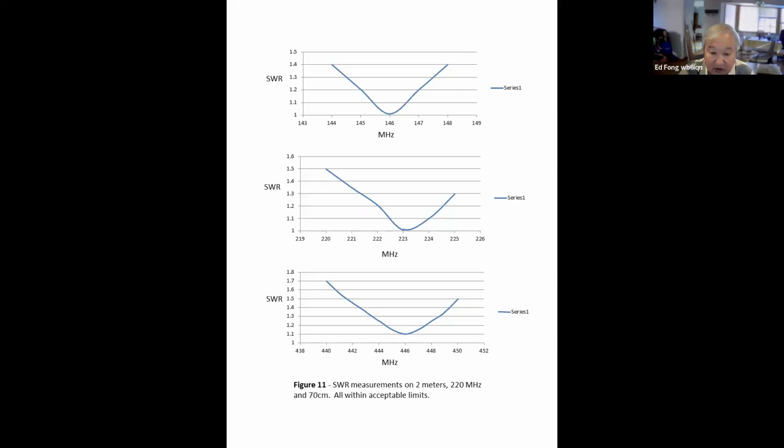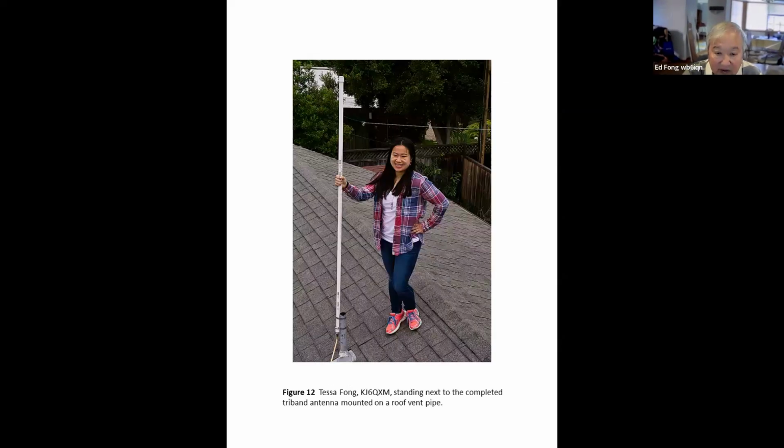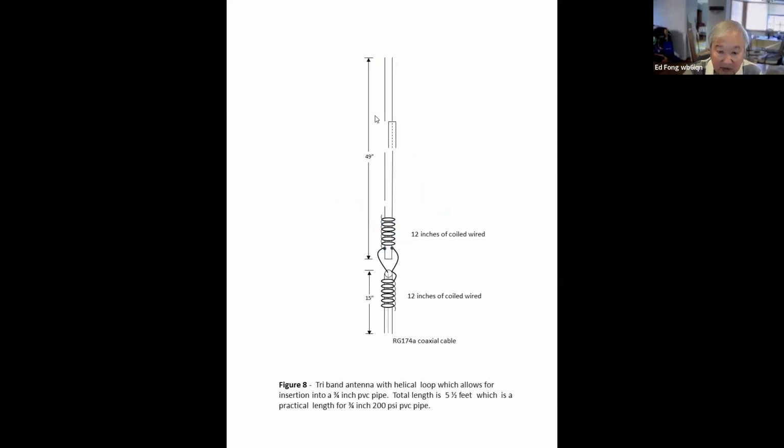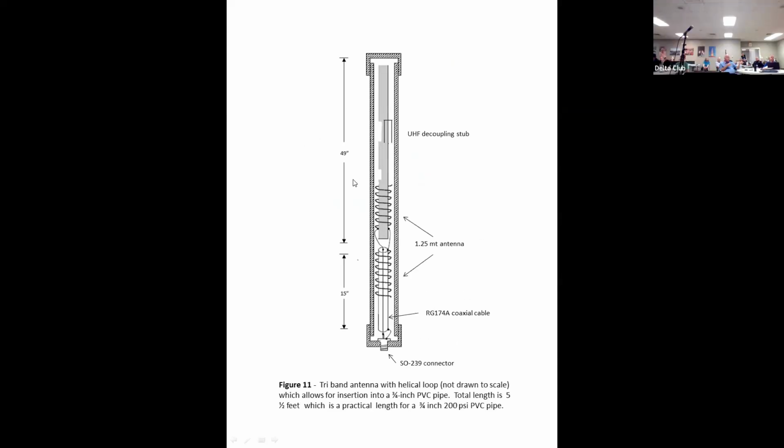Oh, it's interesting. So when you tune this, you pop it out. It turns out if you scratch the coils, you will lower the frequency. Scratch them symmetrically. Very important to try to do it as symmetric as possible. Otherwise, you get common mode currents. And if you compress them, you will raise the frequency. So just do it very carefully.